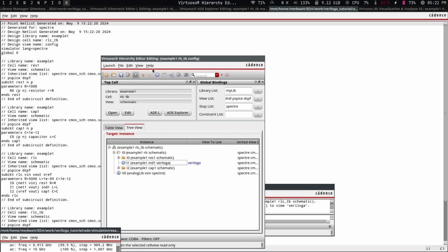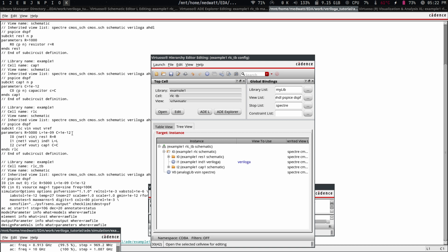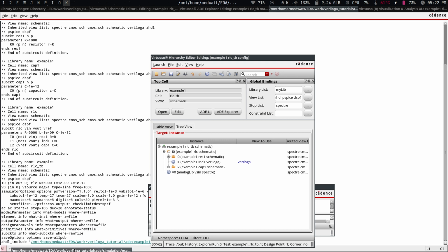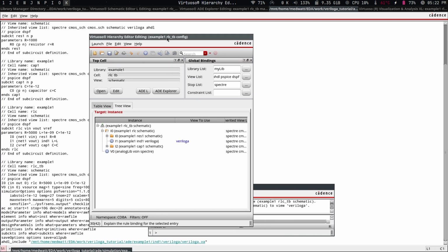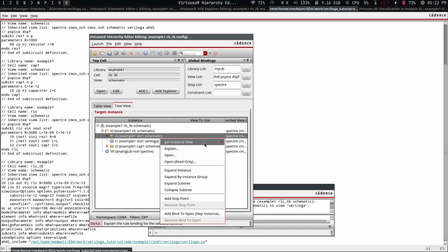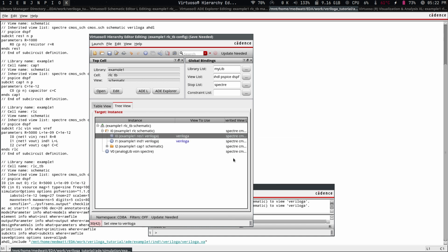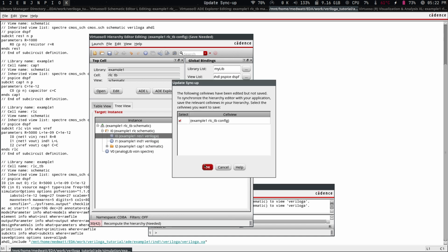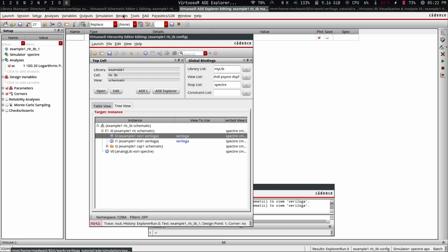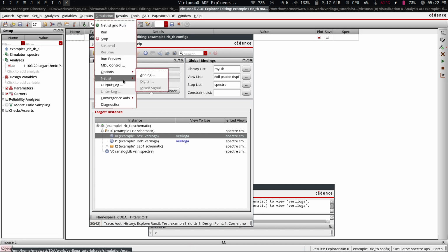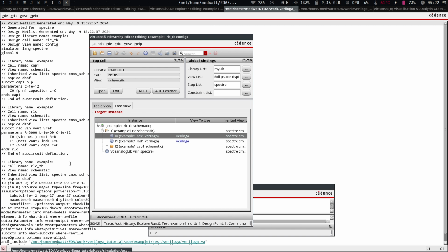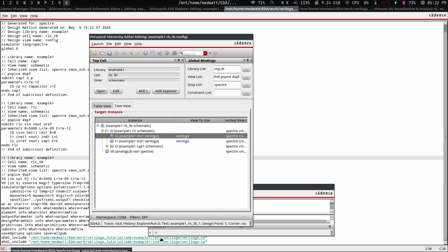Let's see now the netlist display. Okay, we should see that AHDL include, it's including only the one for the inductor. You can see, because that's the only one we did, to show that we're actually doing something correct. We can do it like that. One more time. Let's do simulation, netlist, recreate. So now we have both of them for the resistor and the inductor.